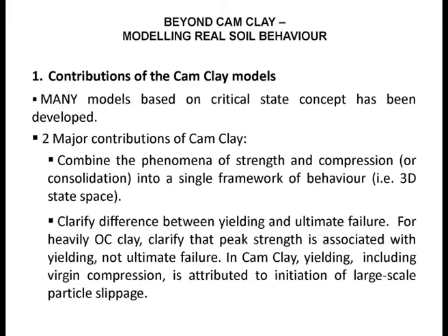Okay? The second thing about the Cam clay behavior is that Cam clay makes a very clear difference between peak strength and ultimate strength. And as far as Cam clay is concerned, failure is ultimate strength. Okay? Peak strength is basically associated with yielding, more associated with yielding rather than ultimate failure. Okay? And in Cam clay, yielding, including virgin compression, that means this virgin compression line, is attributed to